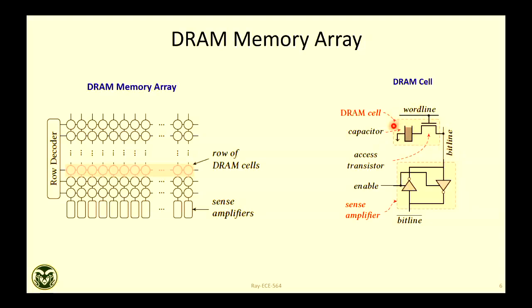Now, based on whether the capacitor is charged or discharged, after sensing, the bitline voltage will go up or down, and that's how you sense. Then the sense amplifier will amplify that little difference, and it will raise the bitline either to VDD or ground. So you start midway, VDD by 2, and then based on the data, the data will be sensed. Then it will be written right back on the same capacitor, because DRAM read is a destructive read, if you recall.